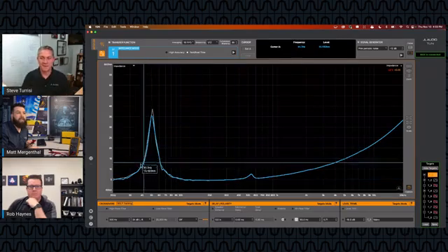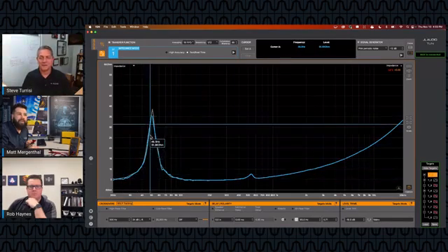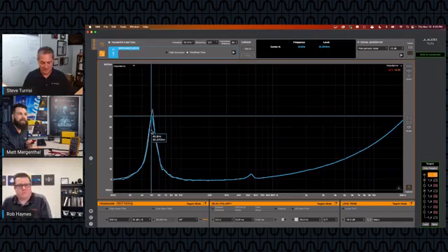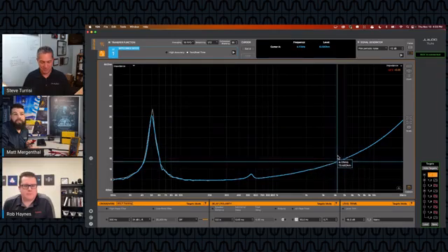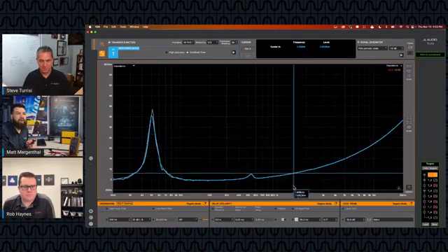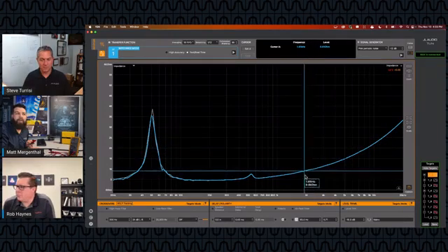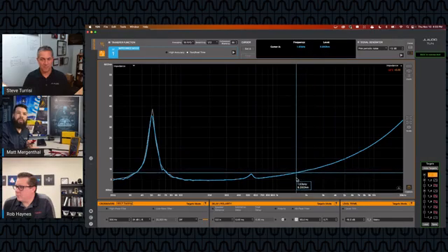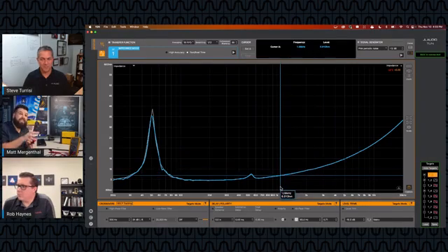This has to be a low frequency driver because it's got a very low FS, about 50 hertz roughly. Then it rises up and tails off, so it doesn't play too well above probably 2K. So based on the data that you see, I'm going to change to some other speakers, and use that data to try and come up with what we're looking at here.